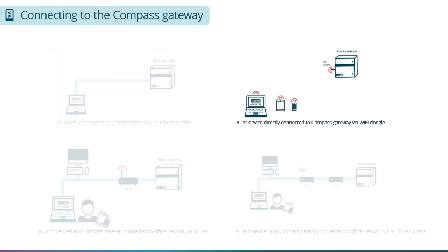It is also possible to connect to the Compass via Wi-Fi. The Wi-Fi option is not recommended for continuous use, but only as a temporary or backup method until you can establish a wired connection. Since the Wi-Fi dongle is inside the Compass panel, the range is extremely low.